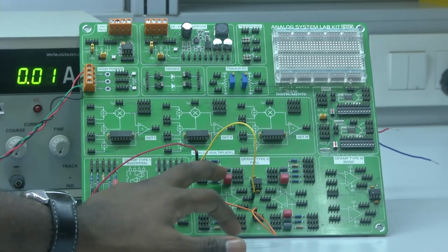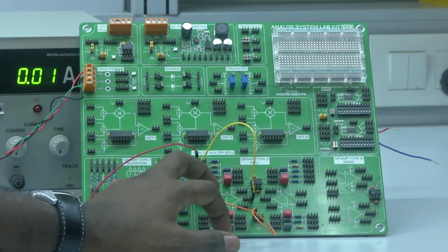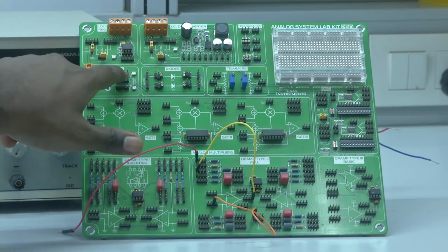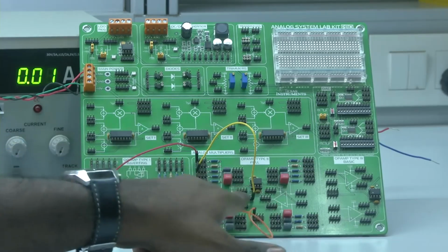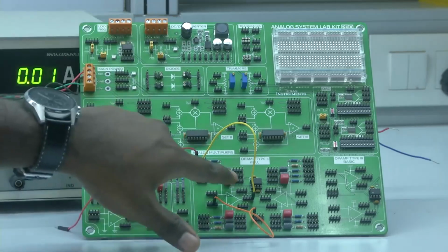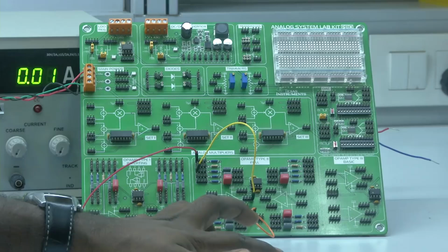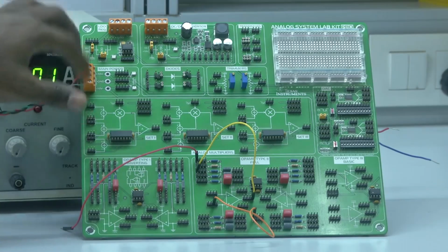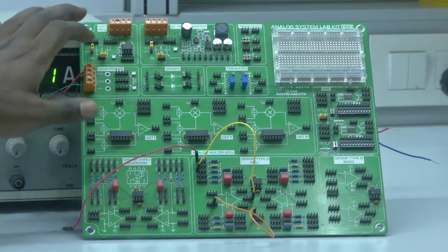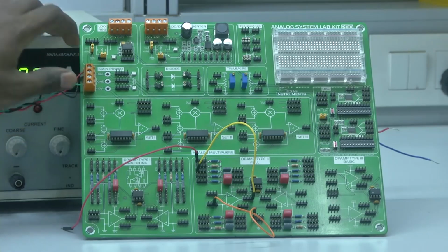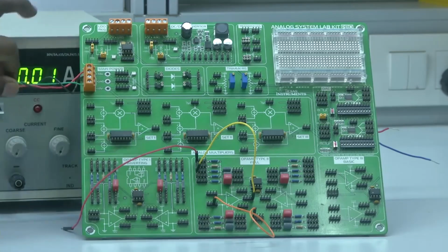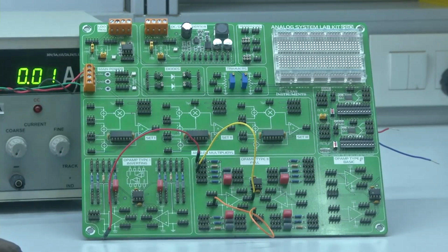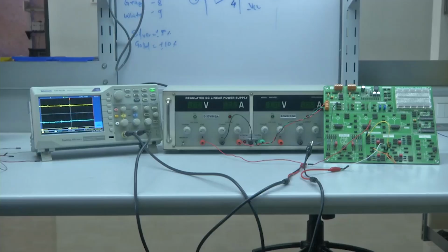In order to understand the working and the gain of this operational amplifier, we have to provide a power supply. The power supply will be connected to this. Since here it is grounded, this and this grounds are the same, internally shorted. Whereas for the positive terminal plus 10 and minus 10, if you connect power to this, automatically the power to all the operational amplifiers will be provided using internal wiring. So, let me connect the output from the linear power supply DC source to these connectors, and we will provide a known input signal at this point and observe the output we are getting. Then we will calculate output by input in order to understand the gain. Let us see the connections.